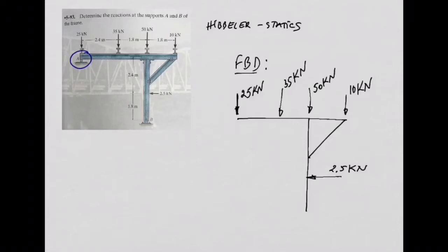Okay? So that's what we agreed last week. Whenever the body we are analyzing is free to move or rotate, there will not be any reaction in that direction. Only if that movement is constrained, that constraint is the meaning of the reaction. The reaction is constraining that movement. Right? So that's what happens here for point A.